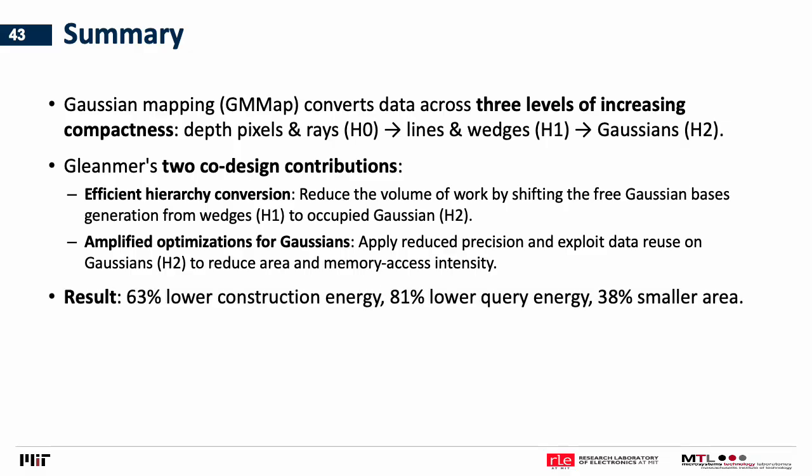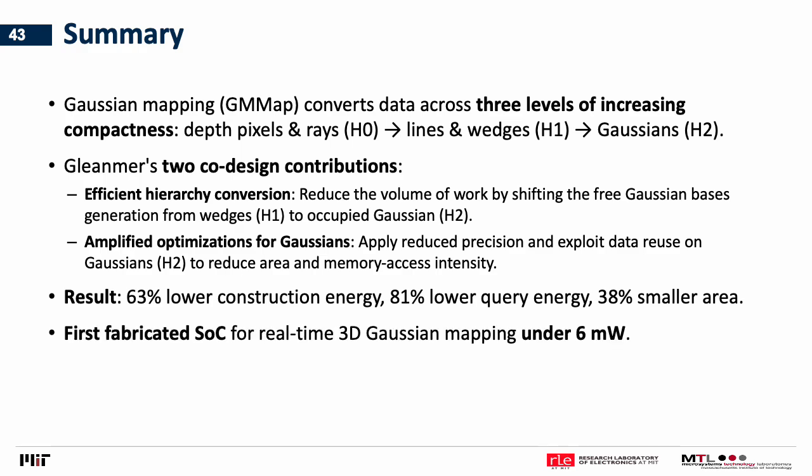With a co-design method, Gleanmer delivers 63% lower construction energy, 81% lower energy on query, and 38% smaller area versus the baseline. Altogether, Gleanmer is the first fabricated SoC for real-time 3D Gaussian mapping under 6 milliwatts, enabling 3D occupancy mapping on a very wide range of edge devices.